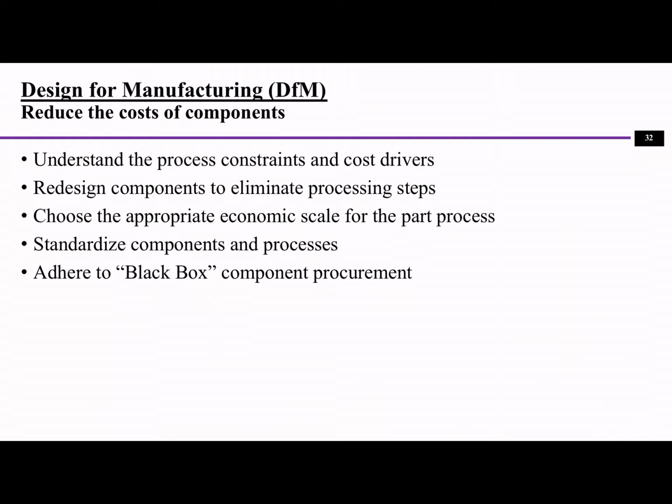And the next one is redesign components to eliminate processing steps. So if you can make several components into one integrated part, it actually eliminates processing steps. So it means you are eliminating machines or human resources, as well as time for making it. So that's also saving money.